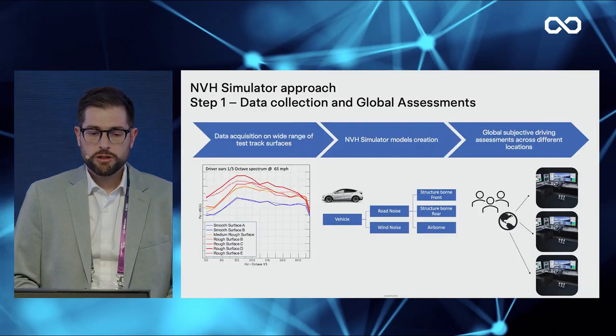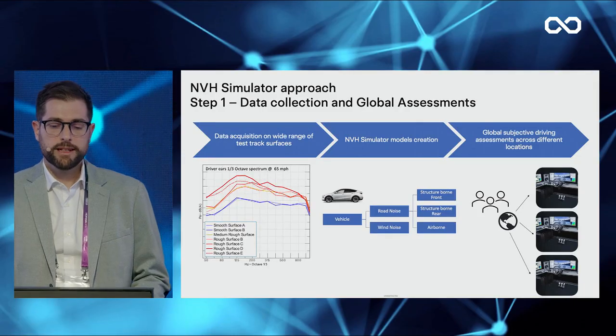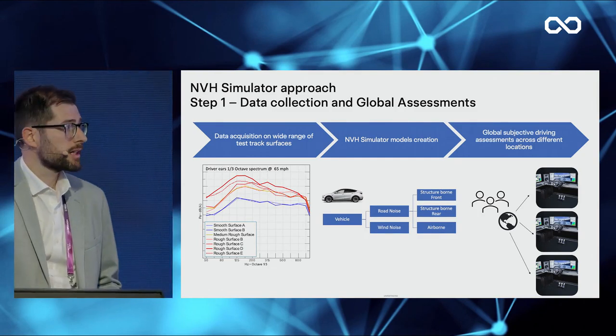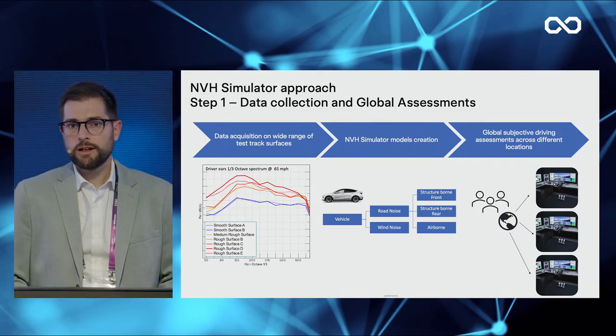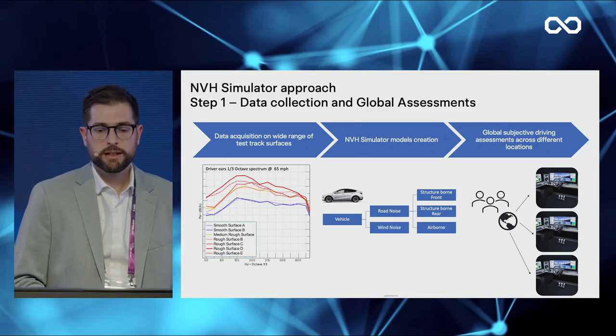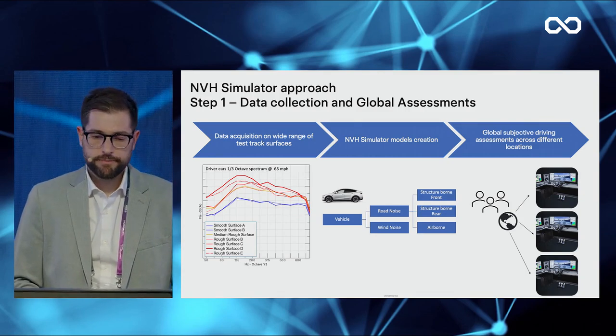To verify this approach, we started by first acquiring data on different surfaces around the globe, and building a simulator model. So we collected all the data in order to be able to discretize the vehicle into its main noise contributors, dividing between road noise and wind noise, and specifically subdividing road noise into structure-borne for the front and rear suspension, and the airborne contribution coming from the tires.